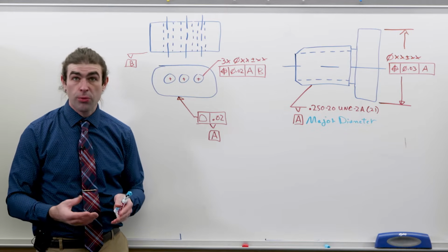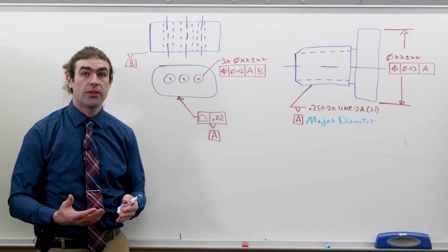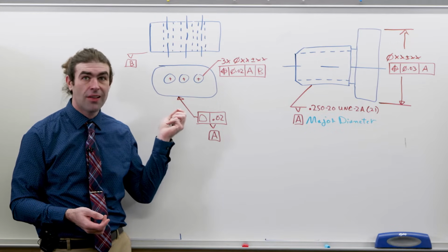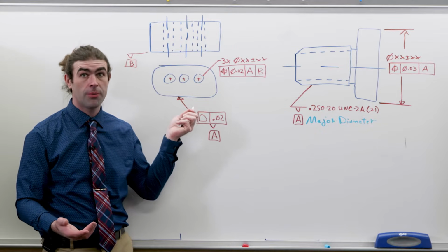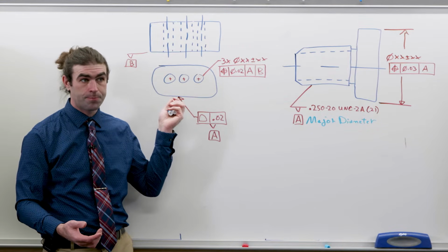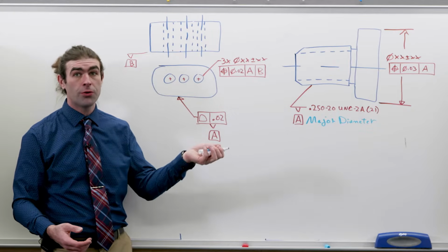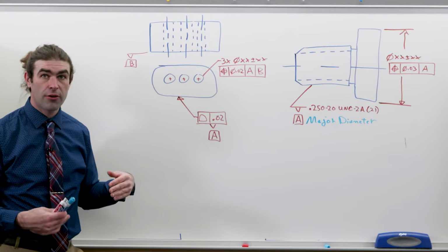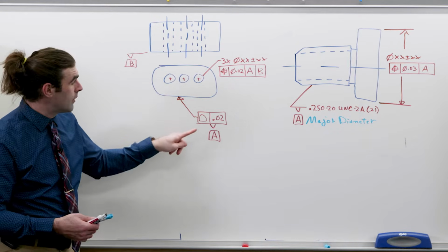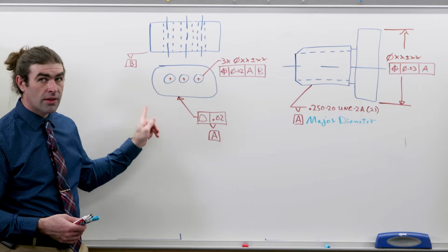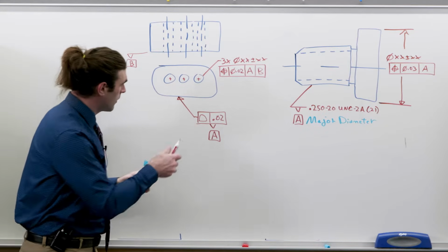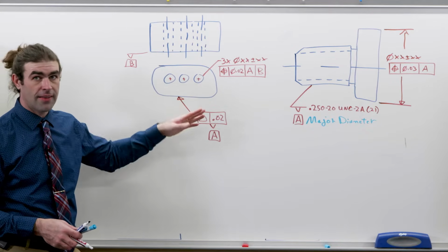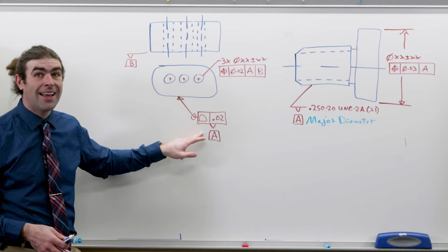So next, you can use profile shapes as a datum. What I'm talking about are irregular features. In this case, I've got a slot shape that's an external feature, a slot shape with 3 holes going through it. You could pick this side or this side to favor and make one of those a datum, or you could tolerance the outside of this with a profile, and I should have an all-around symbol there. Dimension it with basic dimensions. I left that part out, and make that the datum.